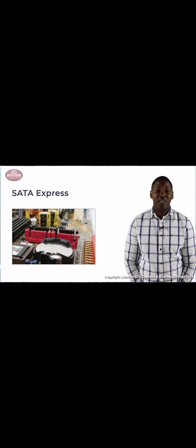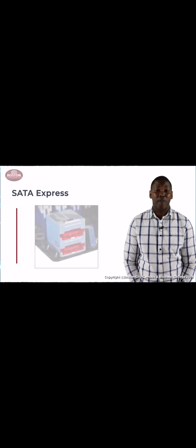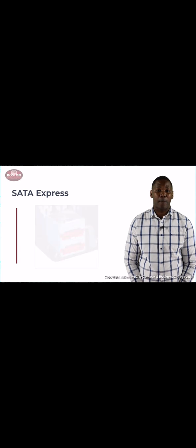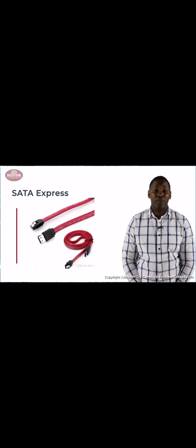In addition to internal SATA connectors, the motherboard or an expansion card can provide external SATA ports for external drives. External SATA, known as eSATA, extends the SATA bus to external devices, as the name would imply. The eSATA drives use connectors similar to internal SATA, but they are keyed differently so you can't mistake one for the other. External SATA uses shielded cable in lengths up to 2 meters outside the PC and is hot swappable.